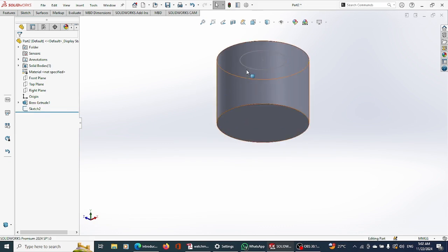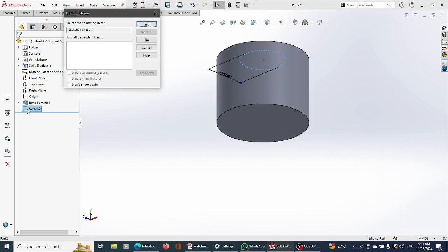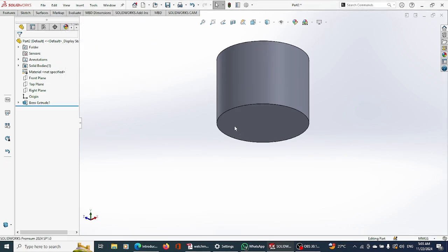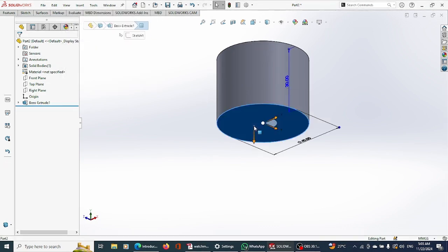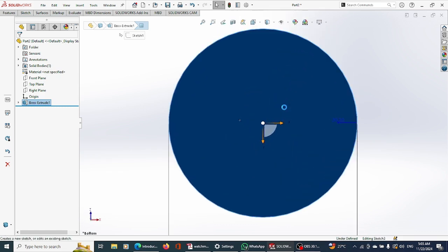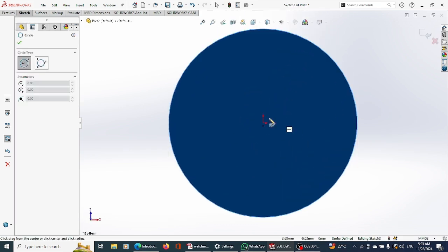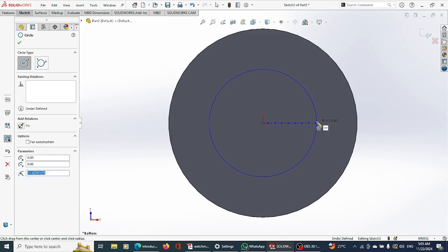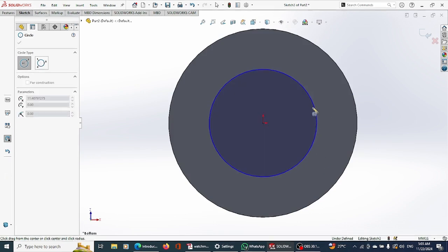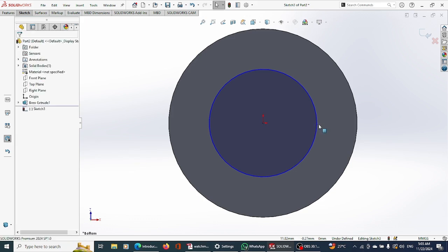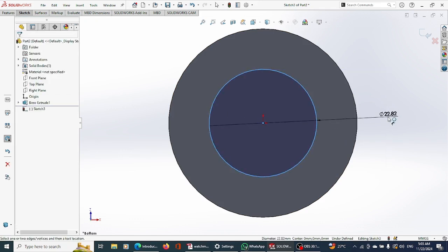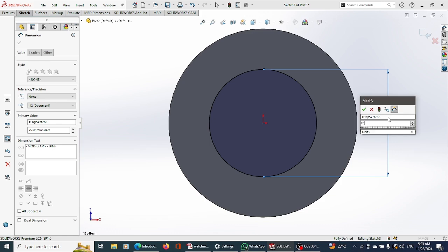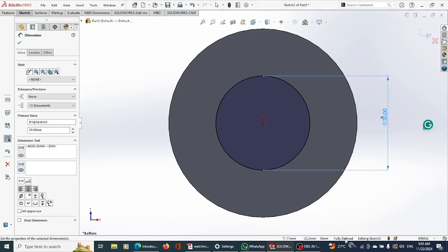feature we just extruded, the extrude feature has gone, but the sketch is still available. I don't need it, I don't want to use it, so I'll delete it. Yes. Now I told you before, you want to draw on this surface, just select it. That highlight comes to choose sketch. I'll draw a circle quickly. Escape. I'll pick my dimension, 2. And then I give it a dimension of 20. So my sketch is still fully defined.